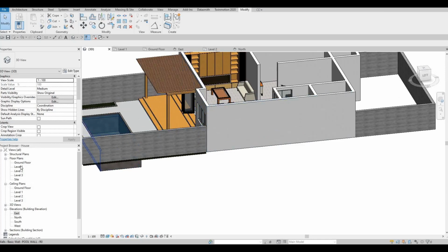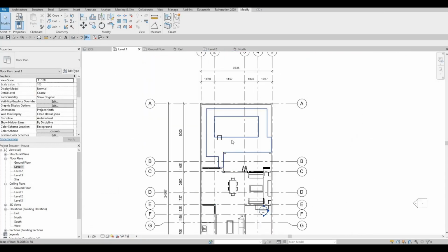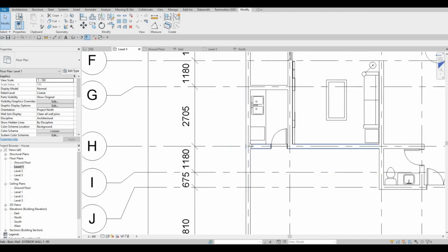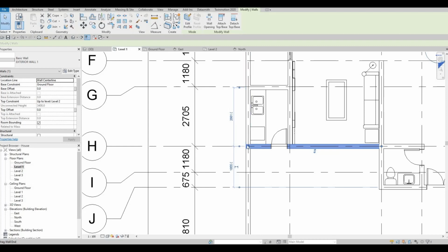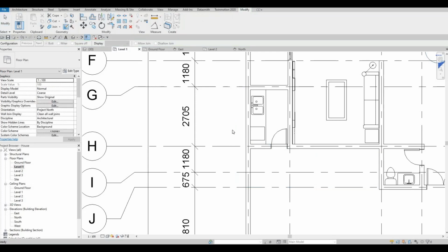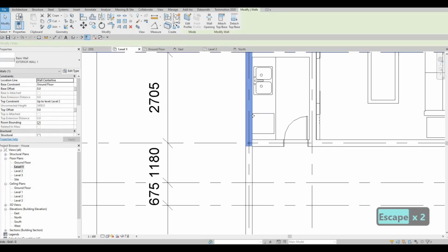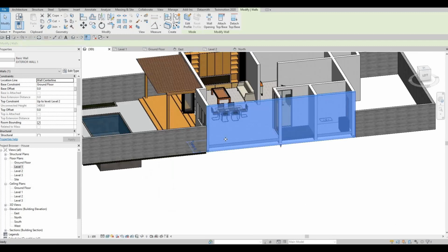And then here, what we could do is we could go to level 1 and we want to double check how this one is being changed. So we need to click on wall joints, select that, and then here we could click on next, and we want it to be on this side, so that once we do that we have everything nicely.